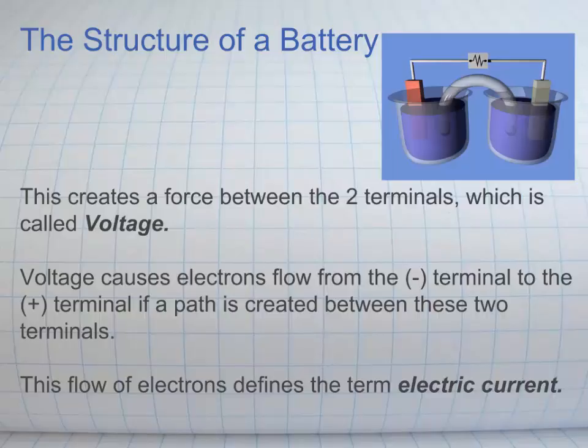So I had to design a system that would completely discharge the battery and then recharge it overnight, so that when the handheld computers go out the next day, they have a full charge instead of dying halfway through the route. My solution was pretty simple. You just put an LED on the battery and let the LED bleed off the power until it gets down below a certain level, and then switch it over to recharge it. So a simple solution to a difficult problem. After NiCad, there were nickel metal hydride. The newer ones are lithium-ion batteries.